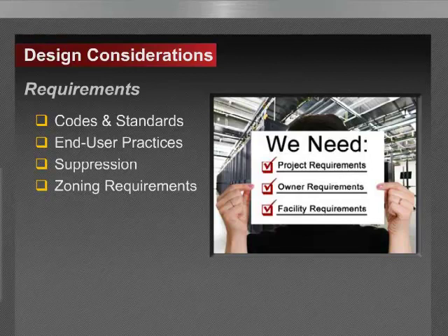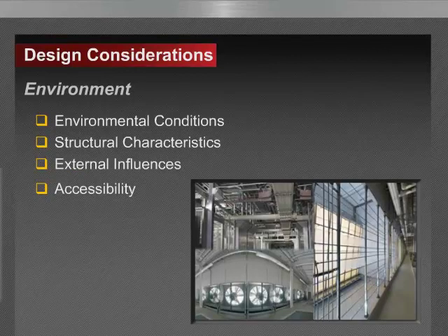So the designer must also take into consideration the environment, such as environmental conditions. What are the cooling configurations and airflow characteristics, direction, magnitude of the area to be protected? What are the structural characteristics? In other words, what effect do parameters such as ceiling height, room geometry, equipment locations, and dimensions have on airflow patterns, ventilation, and smoke detection?